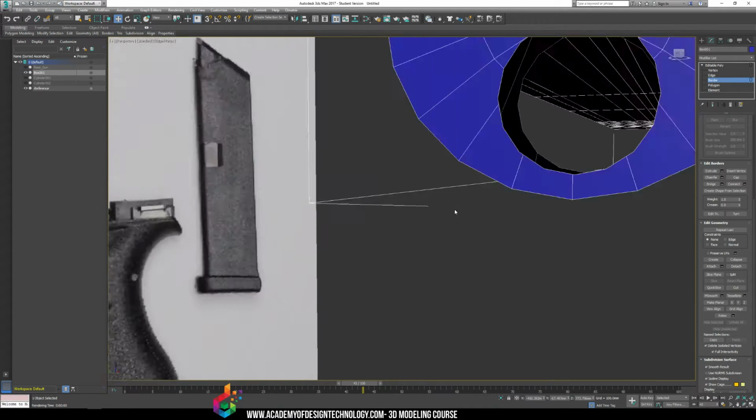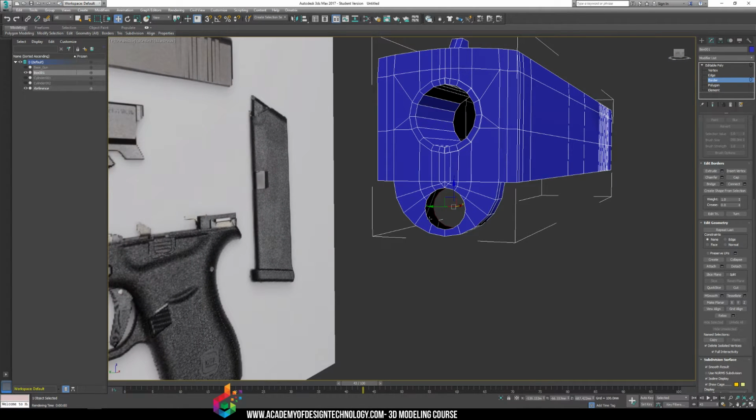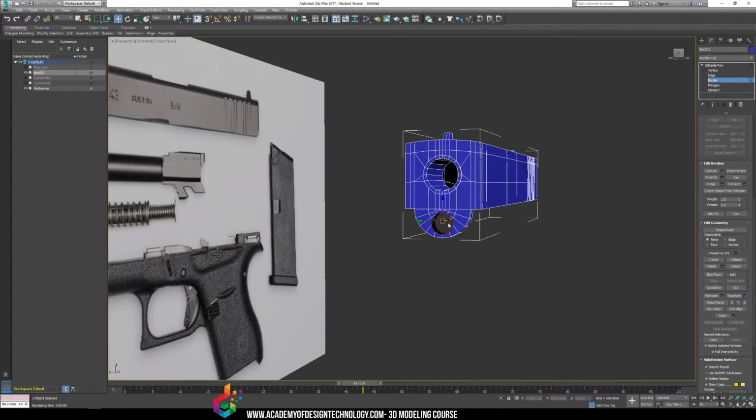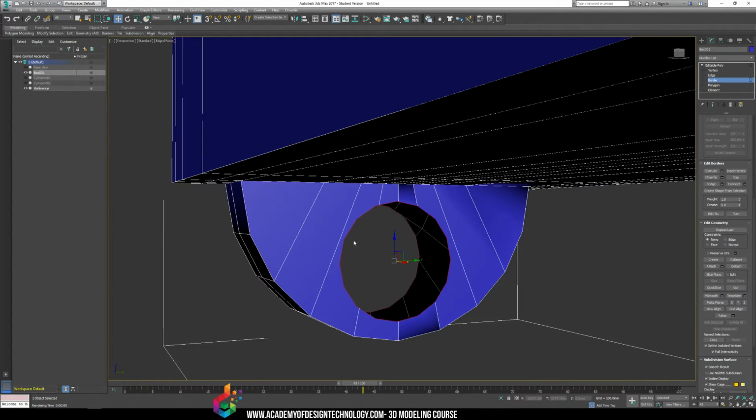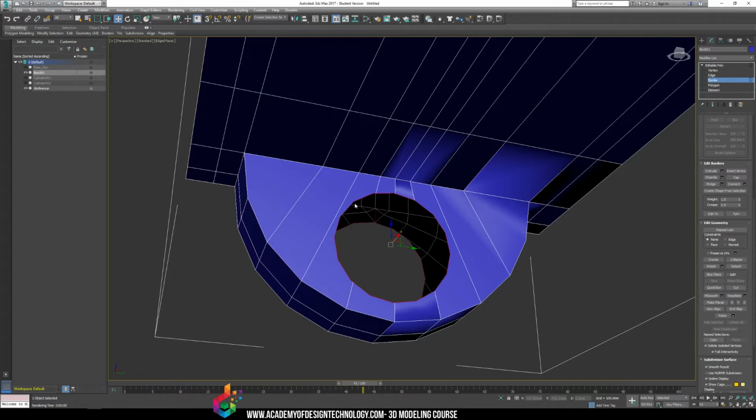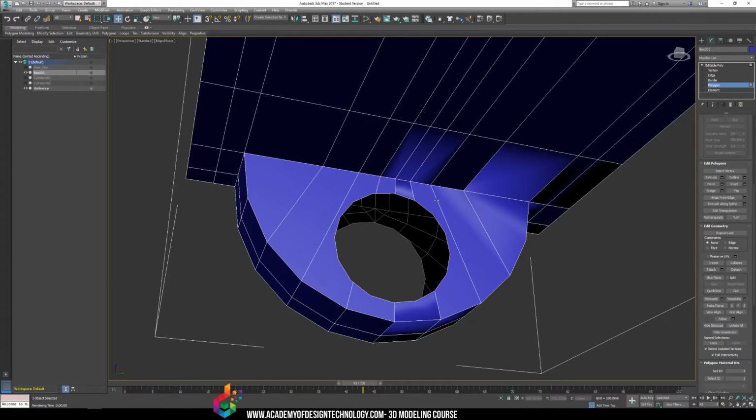And for these right here, you can see we have this empty hole here. Well, that's not going to do. If I grab both these borders and make sure that all the vertex points are welded where I want them to be welded and cut where I need to be cut. So obviously I have a little bit of work to do back here with my smoothing groups and the cutting. I got to take that little bit of extra time.